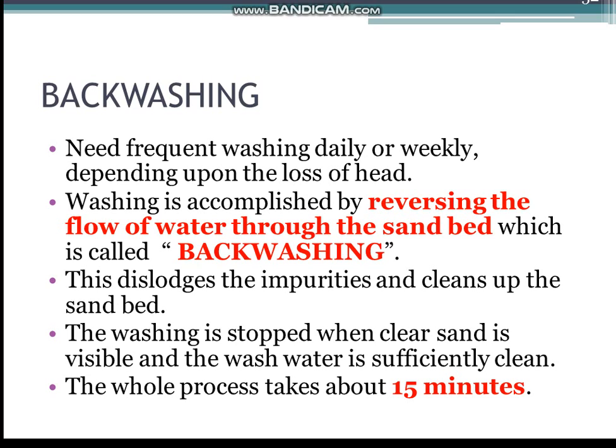Backwashing. Rapid sand filters need frequent washing, daily or weekly, depending upon the loss of head. Washing is accomplished by reversing the flow of water through the sand bed, which is called backwashing. This dislodges the impurities and cleans up the sand bed. The washing is stopped when clear sand is visible and the wash water is sufficiently clear. The whole process of washing takes about 15 minutes. In some rapid sand filters, compressed air is used as a part of the backwashing process.